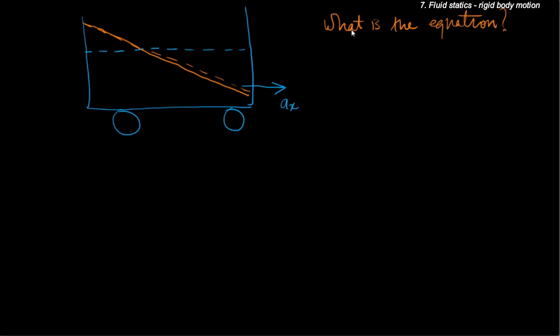So, the way to do it, let us first identify the fact that all the points on the free surface are at ambient pressure. Meaning all over the interface between the water and the air, so this is water, this is air. So at all points on the interface, the pressure will be constant.